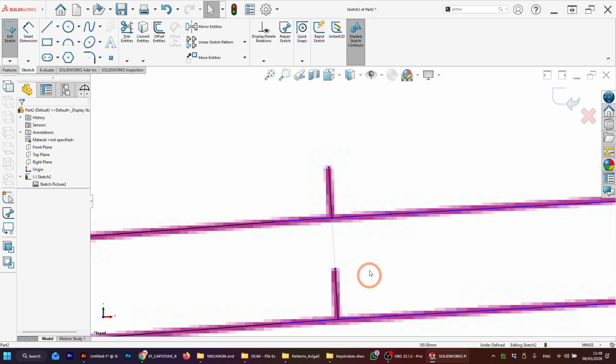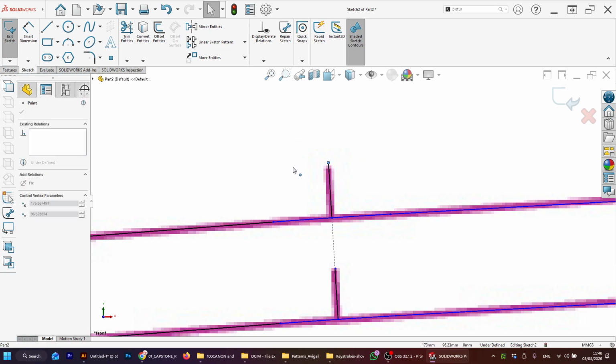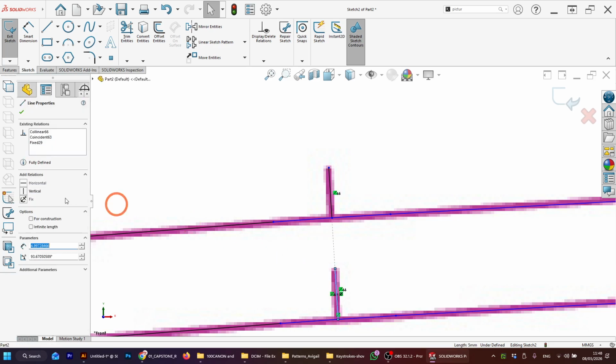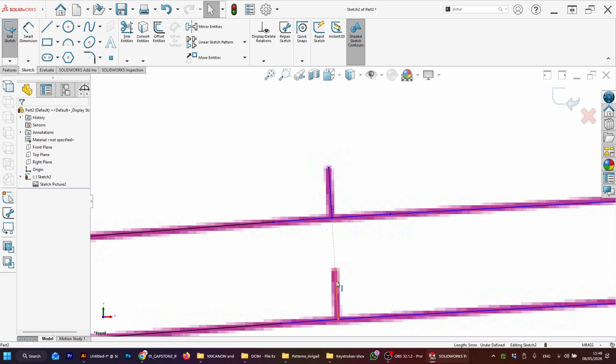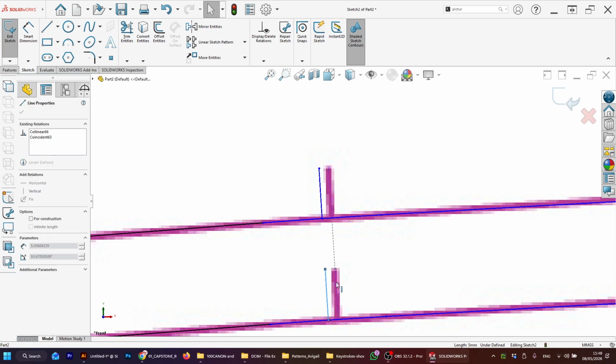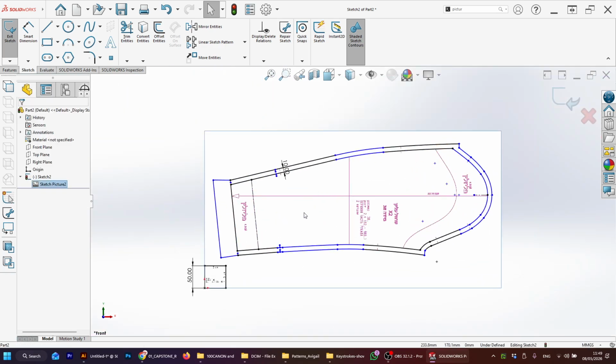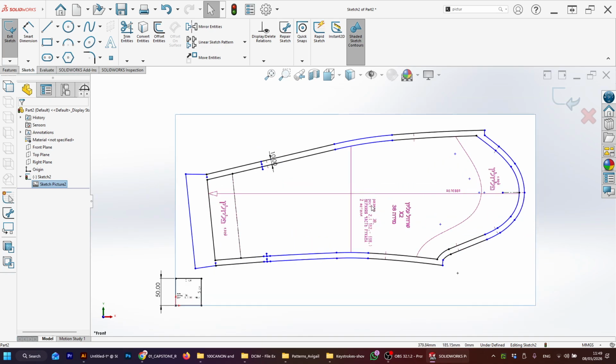Actually, it's good that these mistakes appear because it's going to happen to you. And since SolidWorks is software of decisions, sometimes you need to control the rules. So it's better to sketch it at once and cut it. It was just an opportunity for me to remind you that you can put relations between lines and make them behave. Now these lines will always be aligned together. If I release it, it's not fixed anymore. If I want to move my pick line, the other one moves with it. So it allows you to edit stuff without breaking your head over needing to move this and that. Anyway, you could do that with every pick line. I'm not going to make them because I think you understood the point.